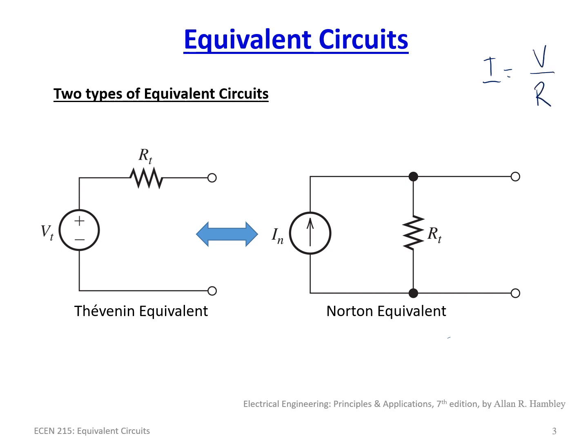So if you do the Thevenin equivalent analysis, which is the next step we're going to show in converting your circuit, and you know RT and VT from that analysis, then getting the Norton equivalent is simply solving for IN and changing the configuration of the circuit to a current source with a parallel resistor.